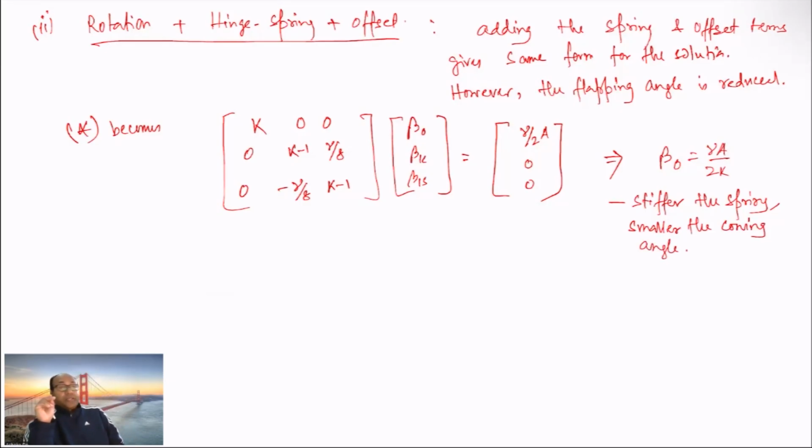So essentially, that's what you get from this particular situation, where you have this balancing act between the aerodynamic moment and the centrifugal force, and on the other side the hinge spring moments, which oppose those two moments.